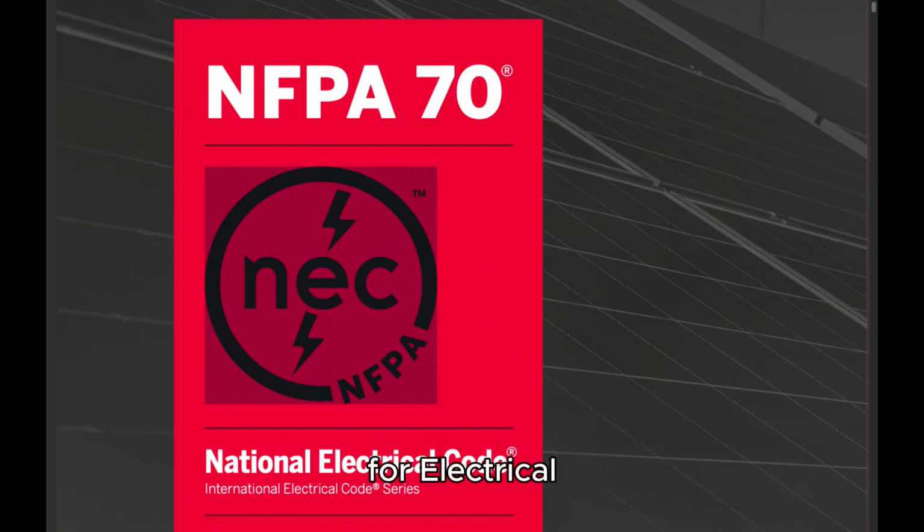110.31 Enclosure for electrical installations. Electrical installations in a vault, room, or closet, or in an area surrounded by a wall, screen, or fence, access to which is controlled by a lock(s) or other approved means, shall be considered to be accessible to qualified persons only. The type of enclosure used in a given case shall be designed and constructed according to the nature and degree of the hazard associated with the installation.